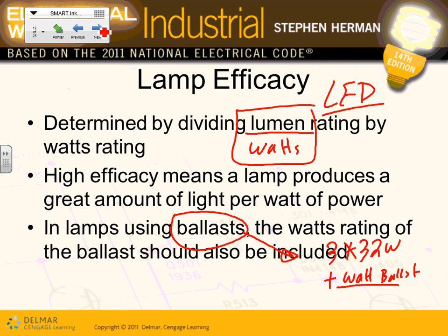Have any of you tried, when we did Visual, multiplying the number of lamps by the watts of each lamp, and then looking at what Visual gives you? Typically Visual gives you more than this. Anybody wondered why? That's because of the losses in the ballast, or if it's LEDs, we have a driver that drives the LED light.